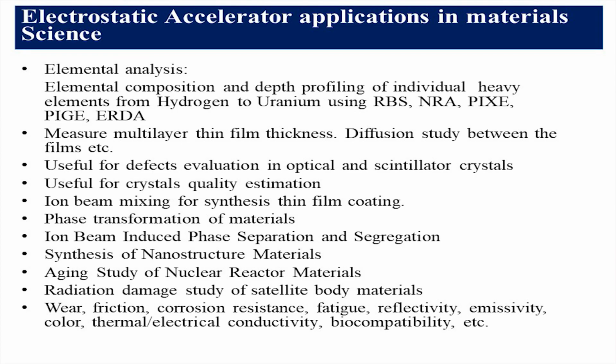Phase transformation is possible through this ion-solid interaction. It is possible. And beam-induced phase separation and segregation could be possible using high energy ion beams. Nanostructure materials you can synthesize through this ion-solid interaction. Aging study of nuclear reactor materials is possible.